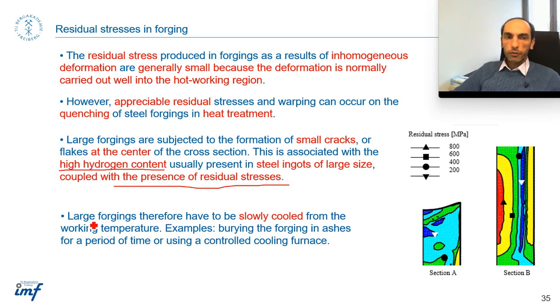And of course the large forging parts should be slowly cooled down, because if you cool them faster, then you will have higher residual stress. So in the conventional way, they bury the forging in ash, or you can put it in a furnace and cool it down slowly.